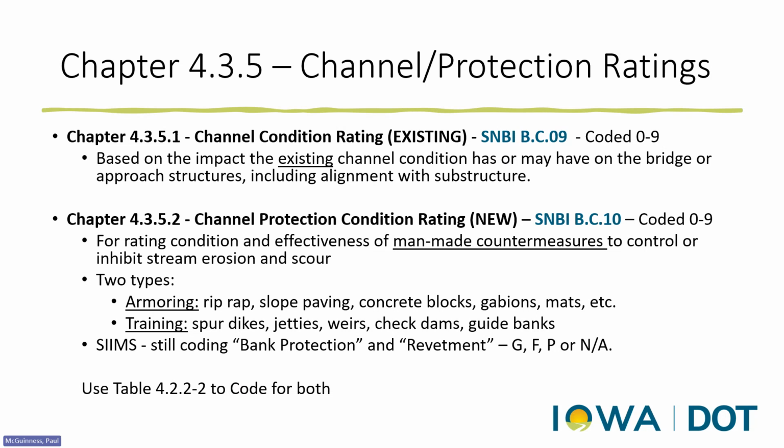And so obviously existing could be alignment issues, scour, undermining, etc. But then when you get into protection, you'll see and be using terminology such as bank protection, revetment, armoring, dikes, spurs, things like that are man-made devices, riprap even, to try to control scour and erosion. So notice the difference between those.